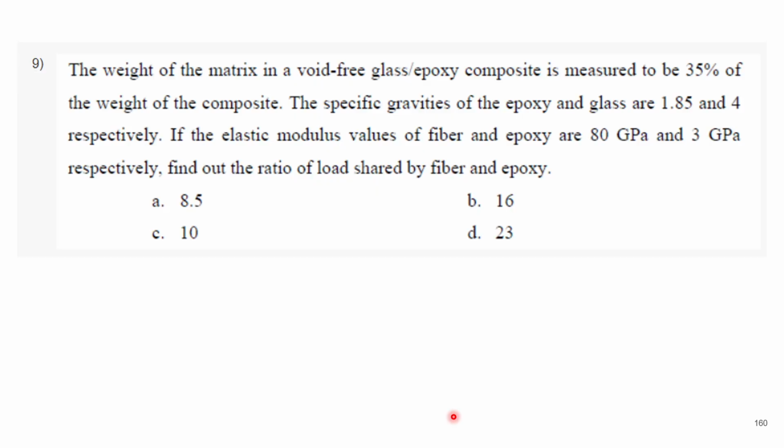Now PC equal to PF plus PM. Okay, so that is the total strength, total load. And therefore, using these relations, we get the PF. So basically using these relations, we get PM by PC value equal to 0.04, because PC equal to 23.716 PM. Okay, and therefore PF by PC equal to 1 minus 0.04, that is 0.96.